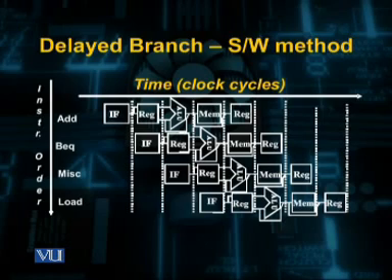If we do not have any such instruction in the program, we can write a no operation at this stage. If 2 stalls are required, then 2 no operations will be used before writing the next instruction. When 2 no operations are included, they will automatically delay the execution of the program by 2 clock cycles.